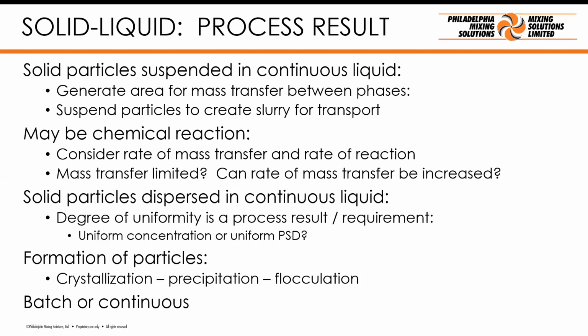And actually, bubble size is very, I'm going to talk about this after we've done solid liquid. It's very difficult to measure bubble size, but you can infer the bubble size from the interfacial area of the bubbles, which you can back out from the kLa, the volumetric mass transfer coefficient. So I'm going to talk about that later. It's actually very difficult to measure bubble size in a stirred tank, but you can infer what the bubble size is from the mass transfer coefficient. Okay, that's fine. Thank you. Yeah, so we'll talk about that later.